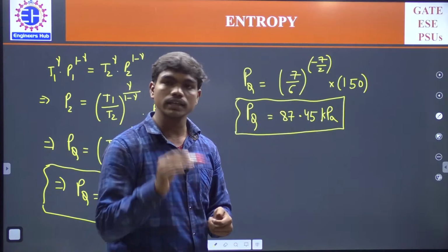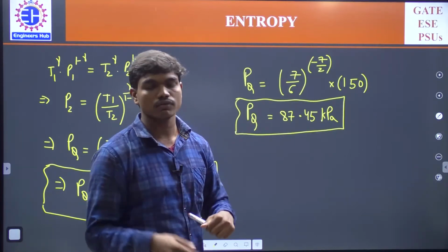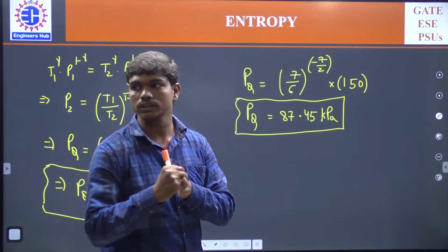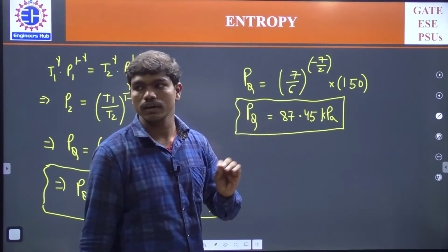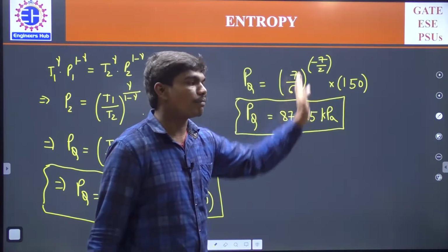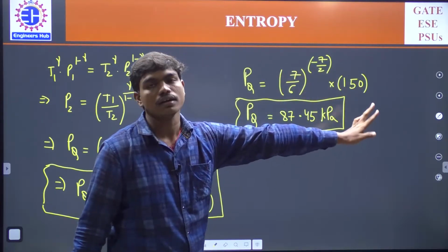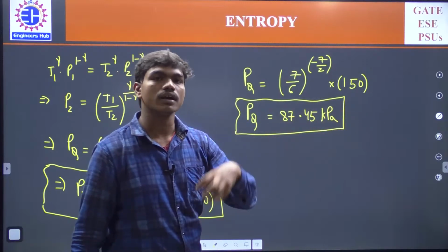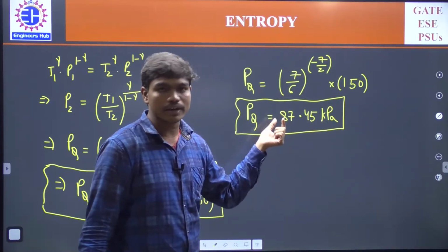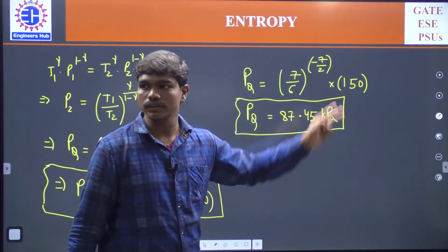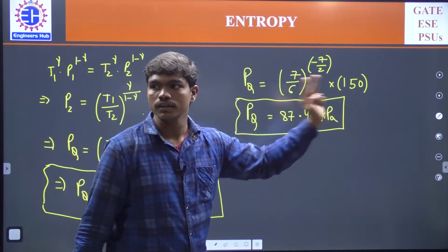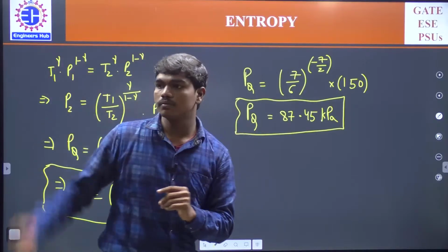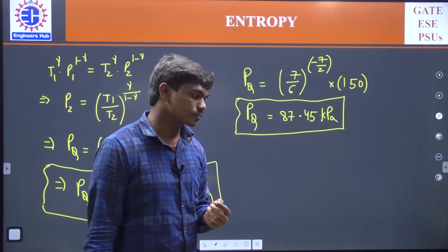So as a result, if the total energy of the fluid decreases, Bernoulli's theorem in fluid mechanics applies, and here air is also a fluid. If there is friction, there will be frictional losses when it flows through the passages. But if the pressure drop has to be minimum, meaning the maximum pressure has to be maintained at the other end, then definitely your process has to be reversible, which means there should not be any irreversibilities like friction. And if the process is given as adiabatic, and you assume reversibility to get the maximum pressure at the other workstation, then the process has to be reversible adiabatic, and you can apply this equation for a reversible adiabatic process.